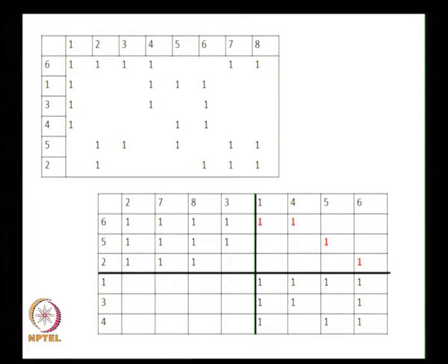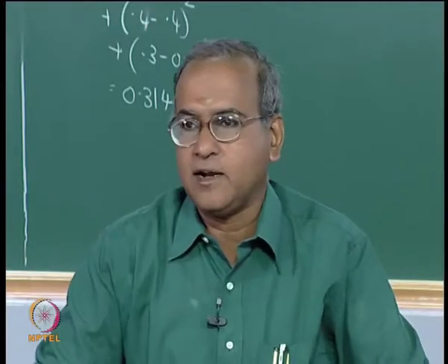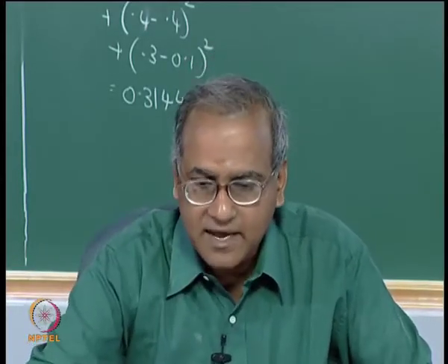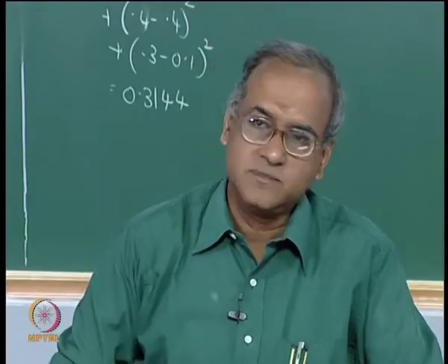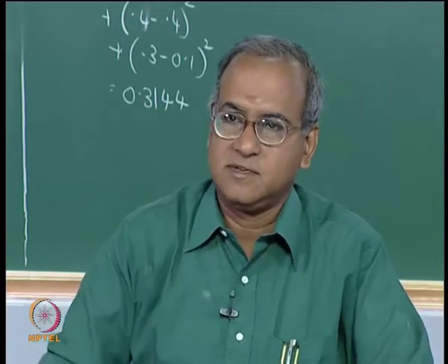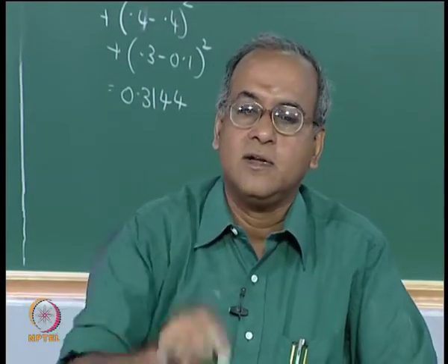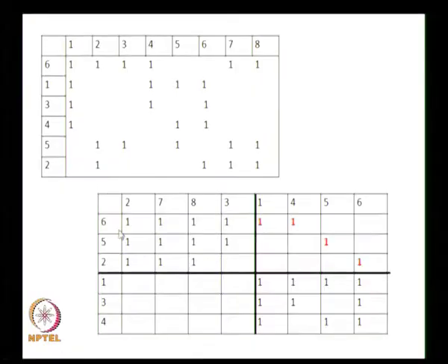The machines will be 2, 5, 6 for the first cell, 1, 3, 4 and 6 for the second cell, and entirely part 5 and part 6 will completely go out of the matrix. Operation subcontracting would mean that we simply take these 2 operations and subcontract only these operations outside. In such a case, after duplication, this machine cell will have 6, 5 and 2, 2, 7, 8, 3.